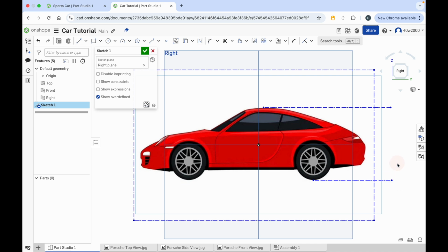Press the escape key to cancel out of that and then click on the dimension tool and click on the 2 dots showing the construction lines that you've just created. Move the mouse cursor outward and you'll get a measurement. I've got 5.80. What I'm going to do is hit Command C to copy that or Control C if you're on a Windows machine and then just press enter. We've copied that number because we're going to use it later.